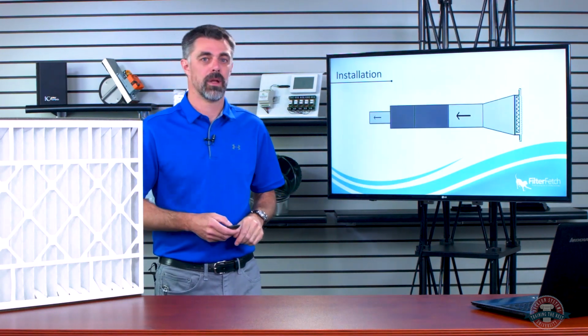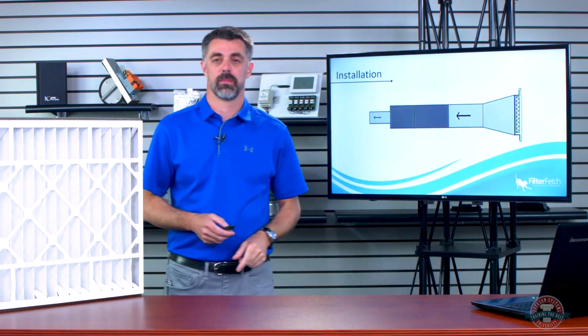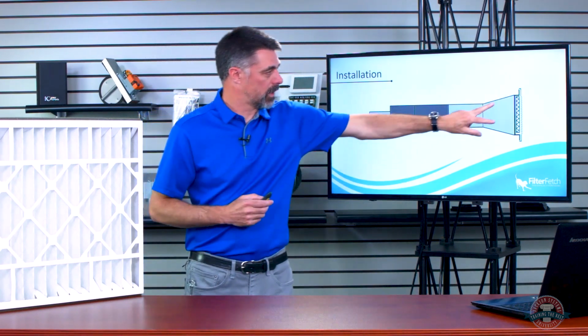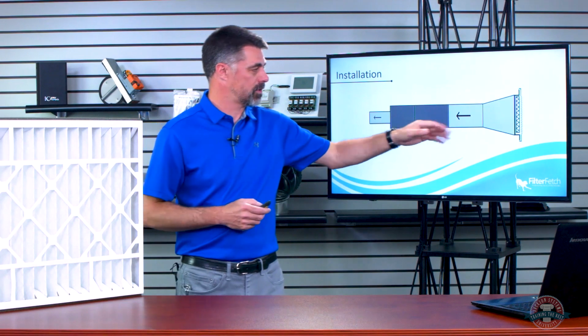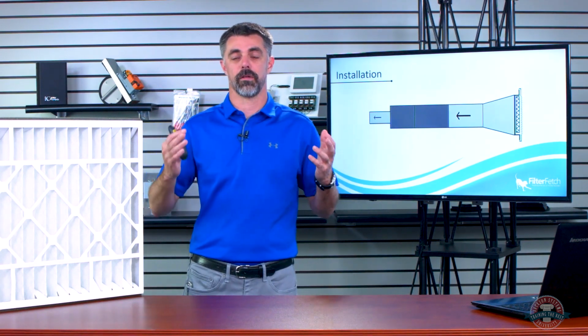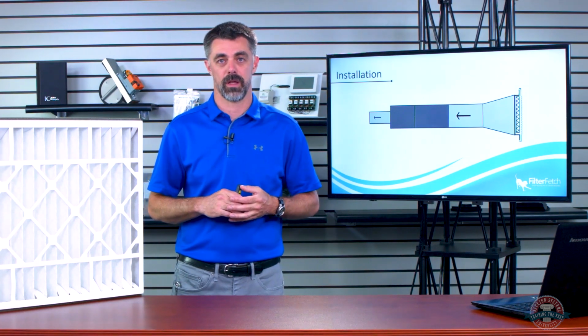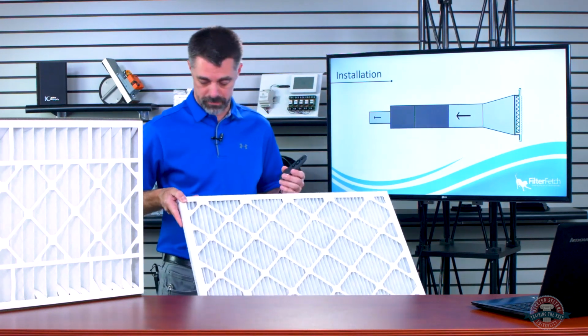Now, again, this system we talked about earlier a little bit. You've got the filter grills out here, and again, I said we need to make sure this is all sealed from the filter grill to the unit, whether this is a package unit or whatever. Something I want to caution you about is on package units, a lot of them have a fixed filter rack size in them from the factory. You need to find out what kind of filters the factory designed that system for, because if you go trying to raise that up to, like this filter right here, which is a Merv 13, I believe.